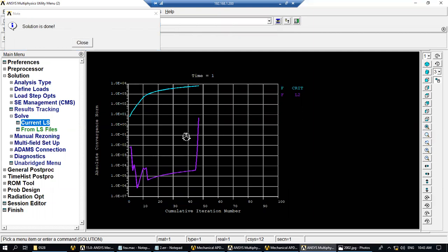The other one is we don't know what is the loading. So we use this increasing load, or let's say progressive collapse kind of analysis, trying to find out what is the ultimate limit state of the structure, or in this case, what is the collapse pressure of our pipe. Okay, you can try different loading to see when it fails. Okay, that's basically everything for today. I can stop the recording now.